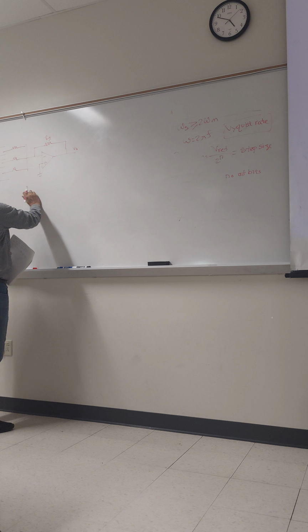Here we give some input voltage, which is connected either to the reference voltage or to the ground. For example, Vref was 3.3 volts, and we saw that 3 is equivalent to 011, so there is a 0.3 volt quantization error. Then he told me that we can minimize it by changing the input voltage, and that is also possible.